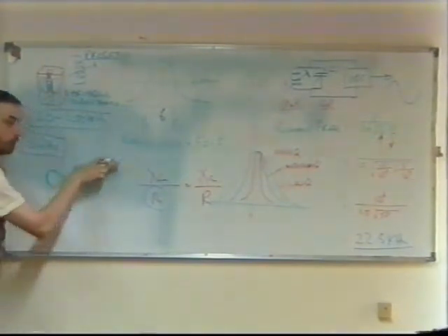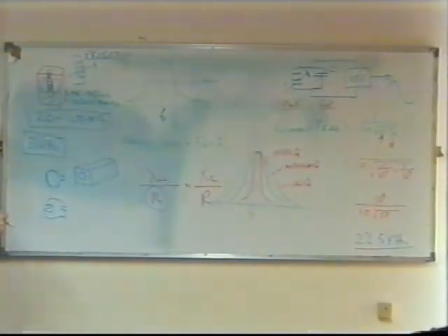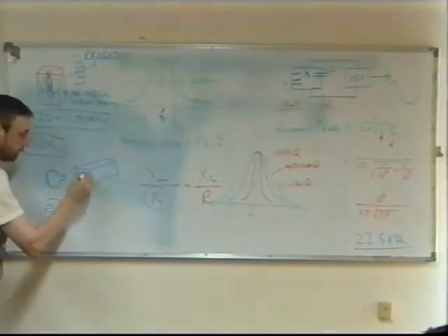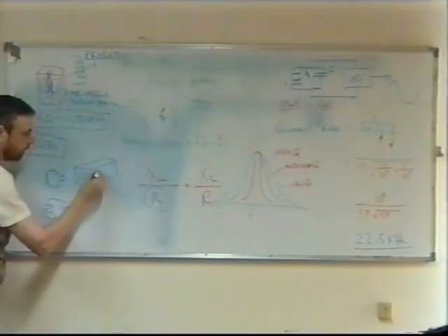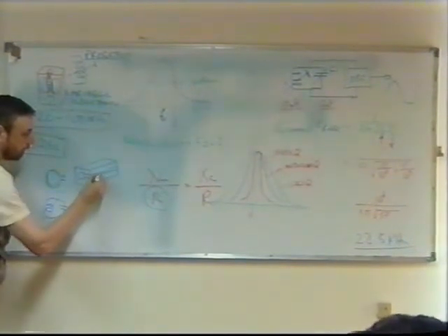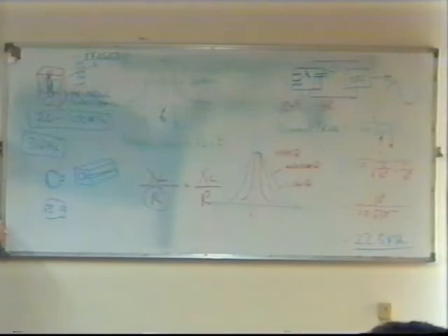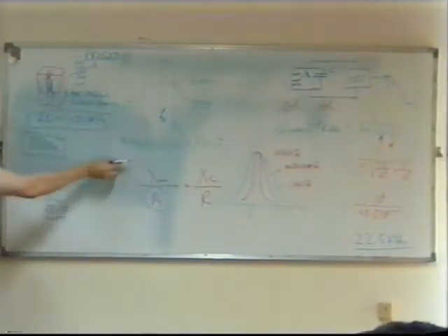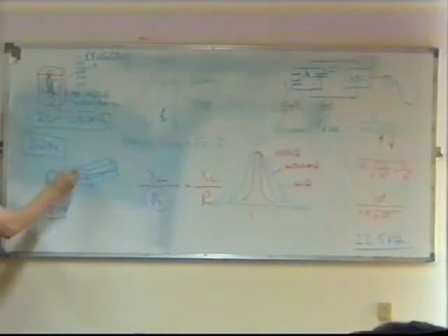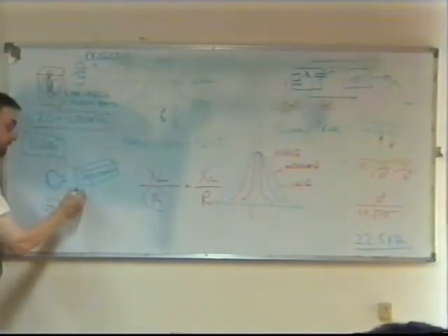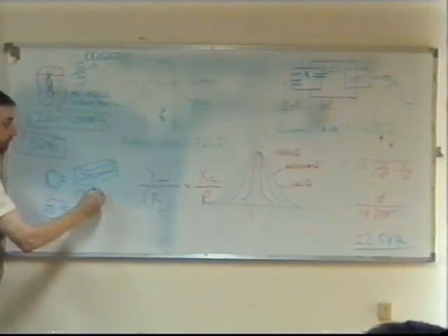So that hole goes right through the solid block of copper. I then machine out a gap there, so that gap runs the length like that. So it's like a keyway through the solid block of copper. Now that is a tuned circuit, and it's called a cavity resonator.